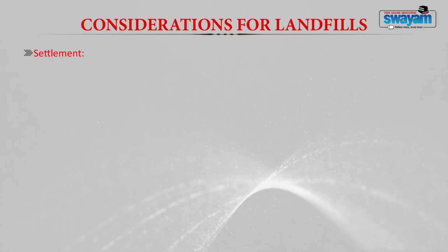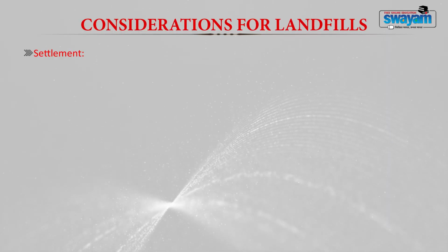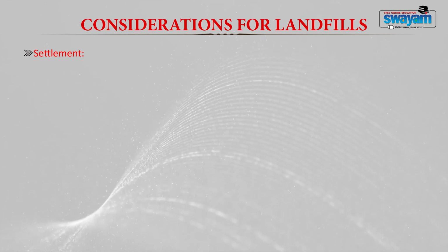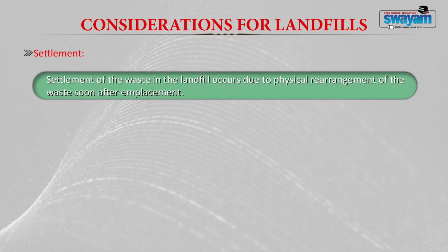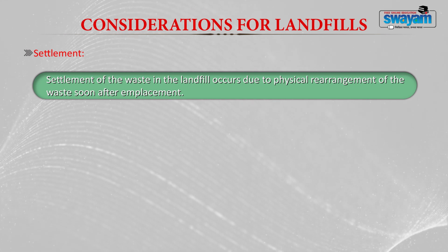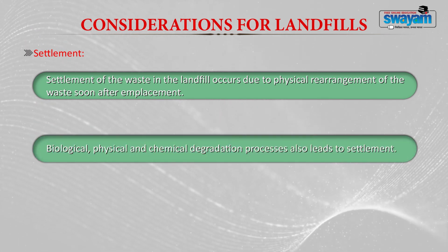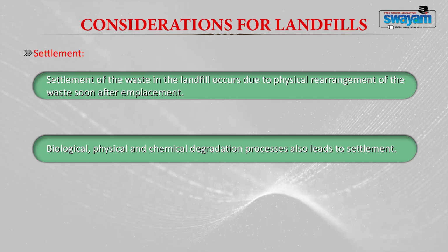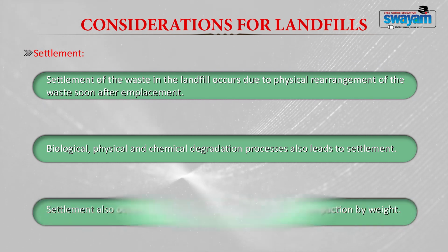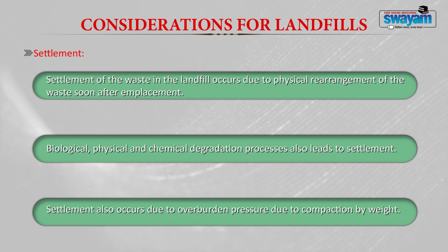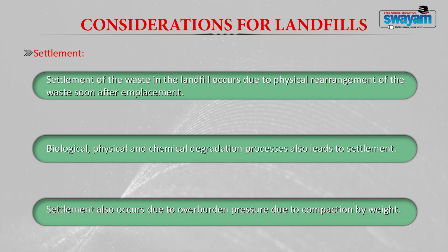The next important factor which you have to consider while designing a landfill is the settlement. Settlement of waste in a landfill occurs due to physical rearrangement of waste as soon as you place it in the landfill, then due to biological, physical and chemical degradation processes, and due to the overburden pressure from compaction by weight. I mean, if you place waste layer by layer one over the other, the top layers will create a pressure on the bottom layer, because of which compaction will occur. This also results in the settlement of waste.